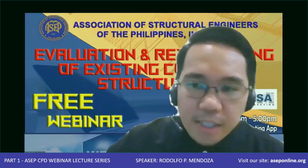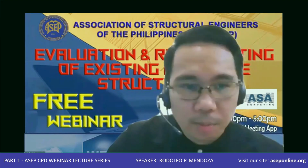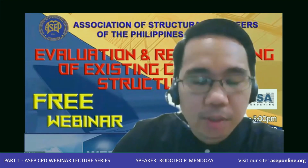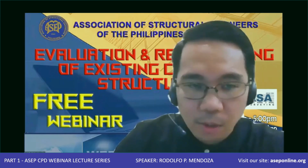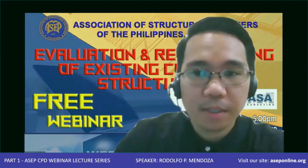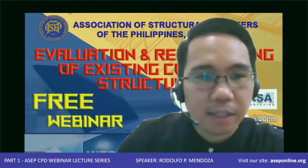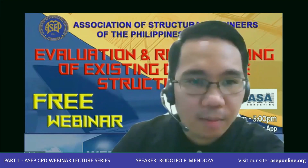Yes, I think in ASCE 41, aside from the two building performance objectives, one for existing structures and the other for new structures, there are other building performance objectives that we call enhanced objectives, and there are also what we call reduced objectives. I think you can reclassify some of the seismic hazard levels in order to qualify for these different levels of objective.